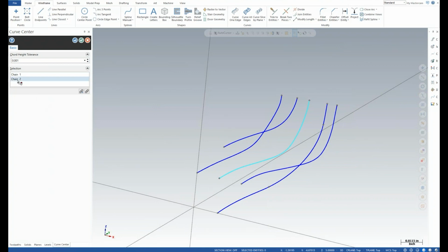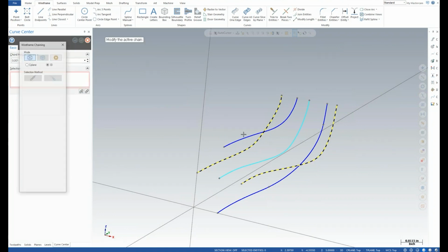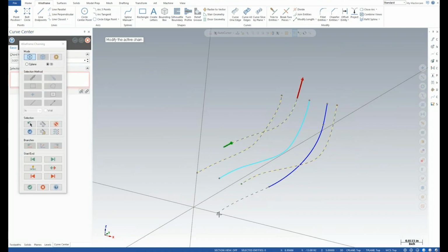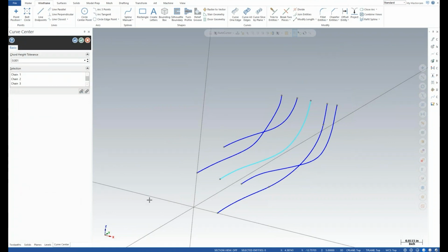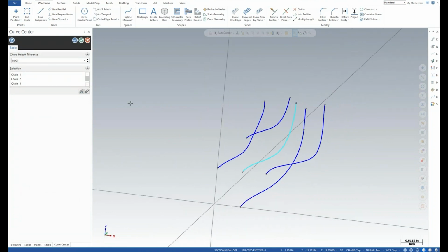And the curves, inside the interaction here in the panel, if I click on one and reverse it, you'll see how that changes. So if you pick a curve going the wrong direction, I don't know if you can hear the train in the background. Anyhow, you pick the curve in the wrong direction, you can go ahead and reverse it. You can also add more chains. So we're just going to go ahead and add these 4 because 4 chains are going to give us a better definition for that center curve.